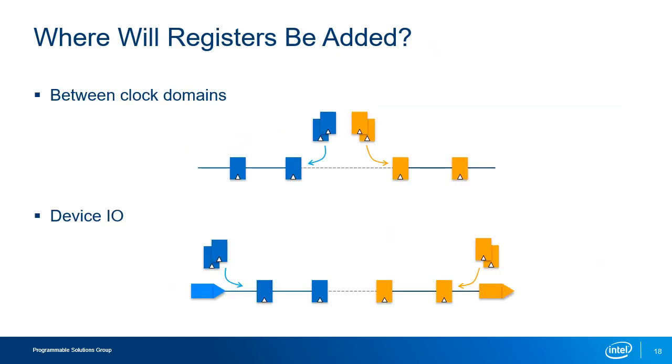When adding registers, if you had to burrow down deep into your RTL to add the register stages at specific design points, that would really mute the usefulness of the recommendations. So, fast forward compile will typically add the registers at more easily accessible locations in the design, such as in between clock domains where you may already have synchronization registers, or at the inputs or outputs to the design. This is assuming you do not have internal endpoints such as asynchronous clears that prevent registers from retiming further. If this is the case, then hyper-retiming may also be required for that particular step.